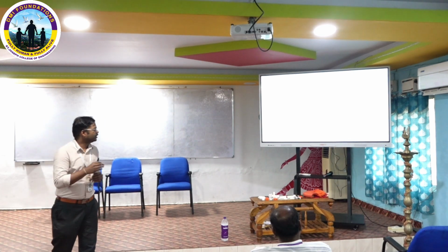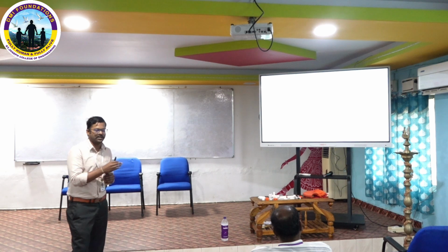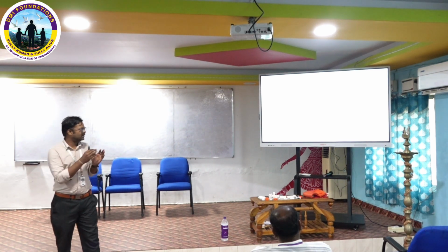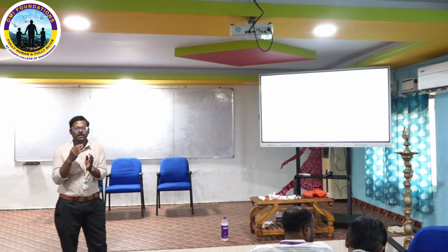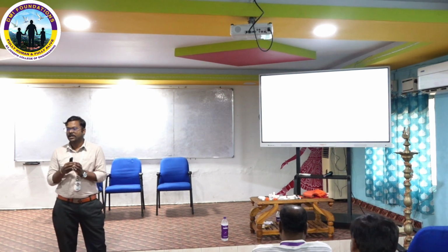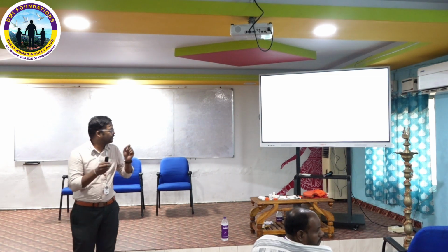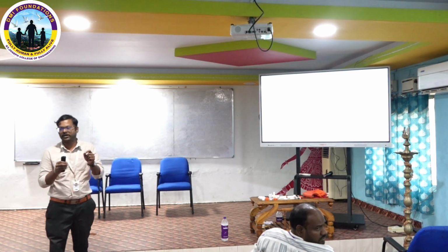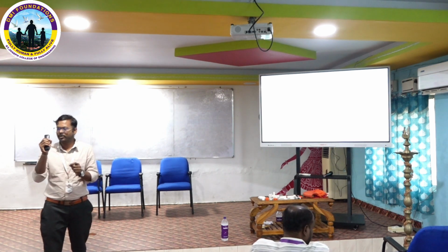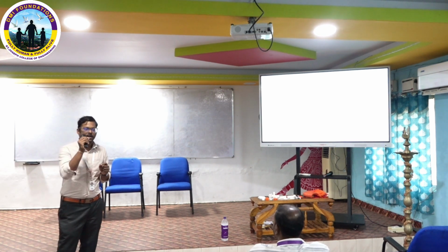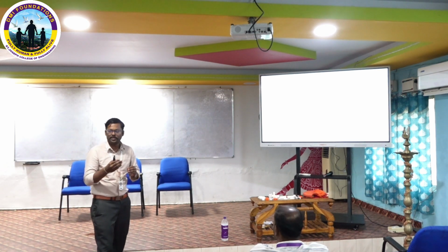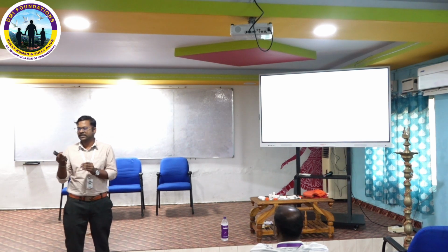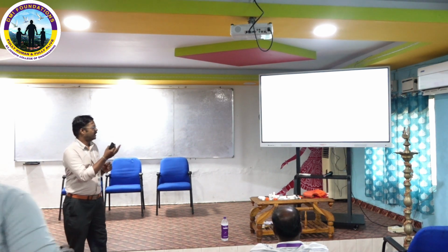In that, we are going to see the powder bed fusion process. Compared to all these 7 categories, powder bed fusion is important to fabricate more complex and customized products. Compared to resin or filament form, we have the material in the form of powder, which is very small in shape. So we can get more surface-finished components compared to wire-based additive manufacturing, which is called FDM, and other processes like direct energy deposition.